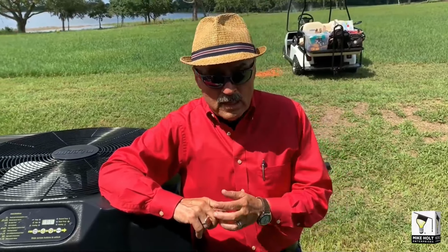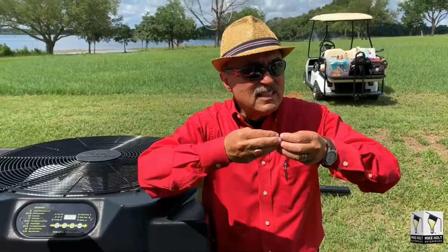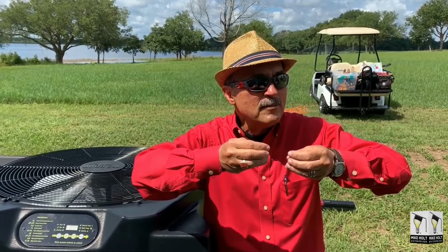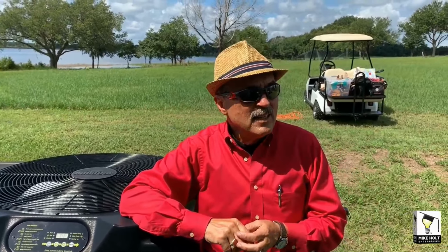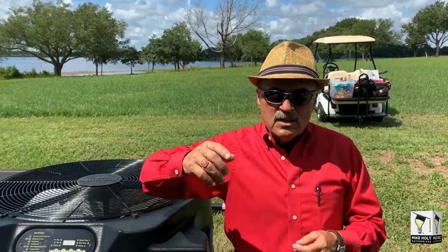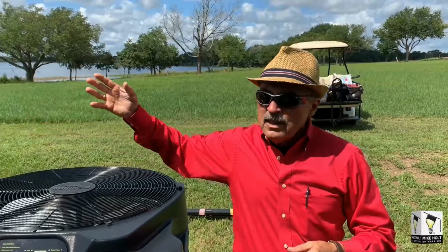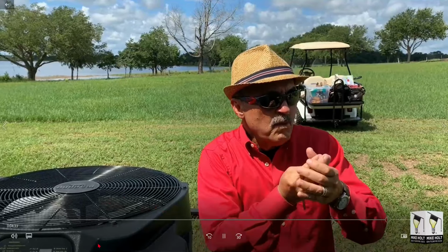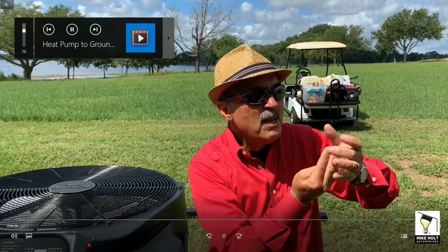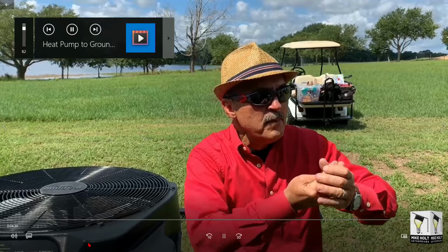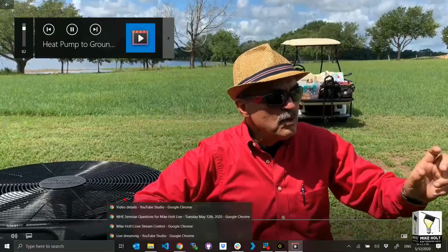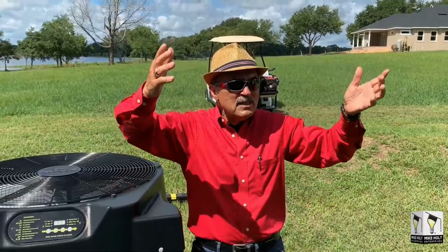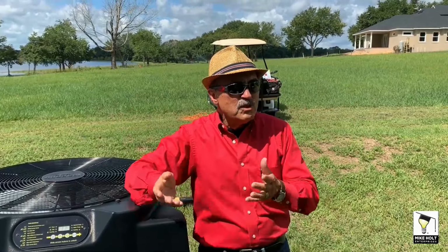Now, as you'll see when we get to the slides, some of the deaths occur because the wiring itself was pulled out of the connector, and the wiring was the effective ground fault current path. It happened to a young man in Iraq. He was taking a shower. He got killed because of the wiring from the generator, military guys, that came to the building. The outside sheath was metal, but when they put it in the connector, the metal didn't make contact, so there was no effective ground fault current path. There was a fault in the plumbing pump motor, so every time they turned on the water, it ended up energizing the water piping system, and he got killed because there was no effective ground fault current path.